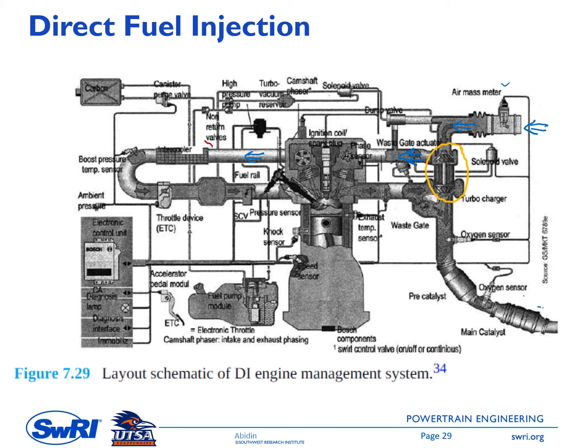So see here, this is a charged air cooler. The purpose of having a charged air cooler is to lower the temperature of the mixture so that we can have an even better volumetric efficiency. And then next, we have several pressure and temperature sensors. And then this one is a throttle device, okay. And all of these devices are controlled by the ECU. So this is the ECU.